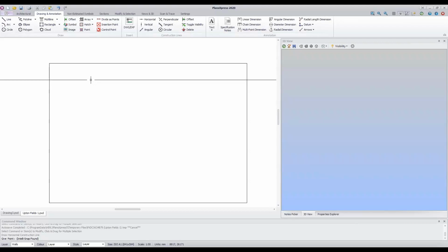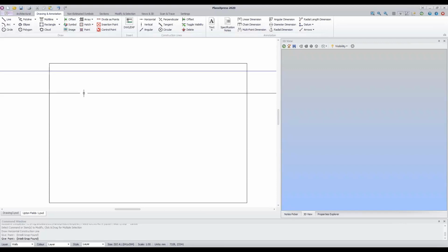So what we're going to do is place this first construction line at the top of the drawing page. This is where, on the top left corner of our page, we're going to lay out our ground floor plans. If you have a look at the main house design, also in your supporting documents pack, you'll see how we're going to lay out the drawing page, so that might be helpful. So place your cursor near the top left of the drawing page, doesn't matter exactly where, but near the top, and then click the left mouse button to place that construction line.